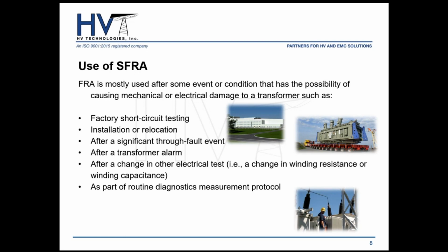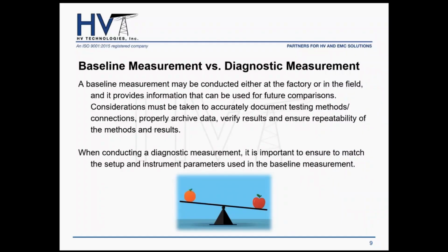And finally, it is always good as a regular routine diagnostics measurement, as a regular maintenance tool. Maybe you have a transformer that is scheduled for maintenance every 6 months. Well, since you're already disconnecting the transformer, you're already running other tests, you might as well run a frequency response analysis as well, and have that as part of your documentation for that specific transformer.